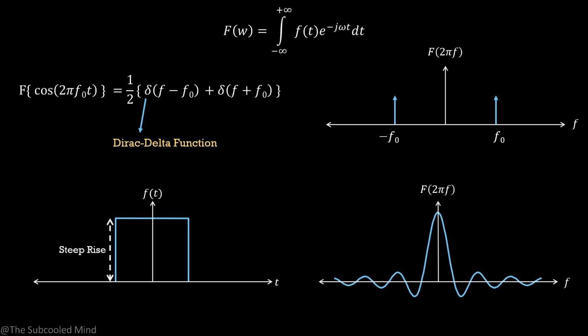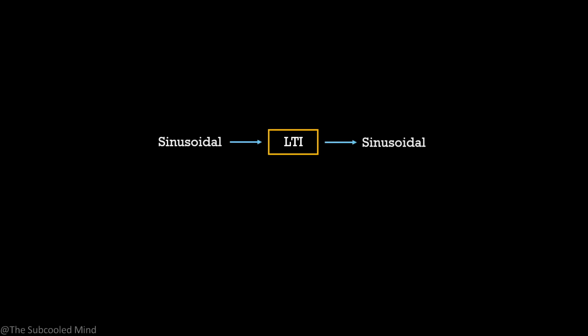Or in other words, what we are doing is breaking any signal as a sum of sinusoids. If you are wondering why we are expressing all signals as sinusoids, this is because sinusoids are extremely easy to deal with and they do not change their shape on passing through a linear time invariant system. What it means is the frequency of the signal will remain the same no matter what linear operation you perform on it. But real life systems work in a different way.